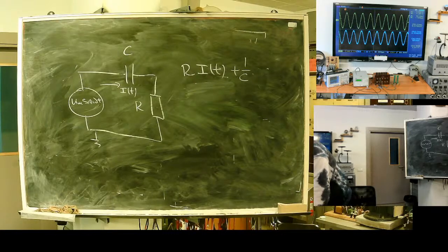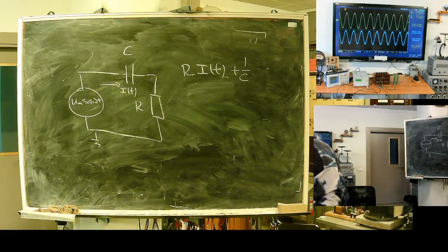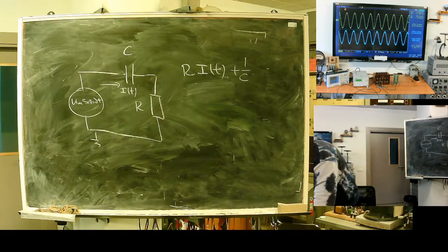I supply energy. I have a smaller capacitor here. It charges. When the voltage reaches a threshold, this neon lamp strikes through. A pulse of current flows through the primary winding of a small transformer, and the xenon lamp gets ignition.